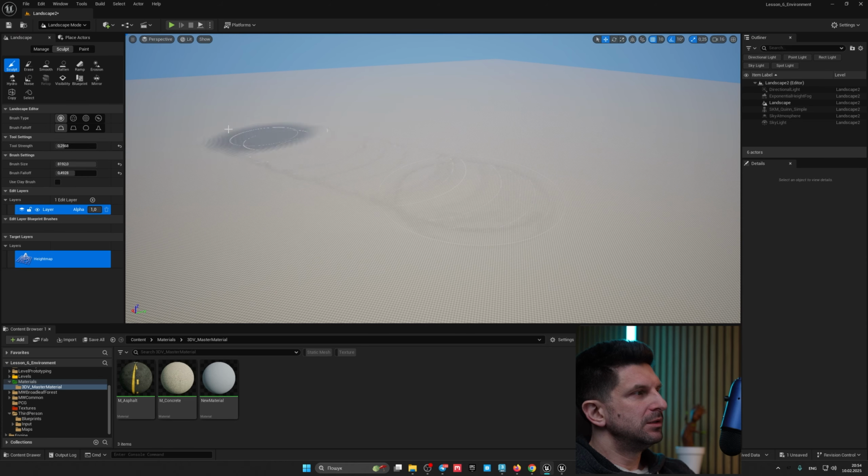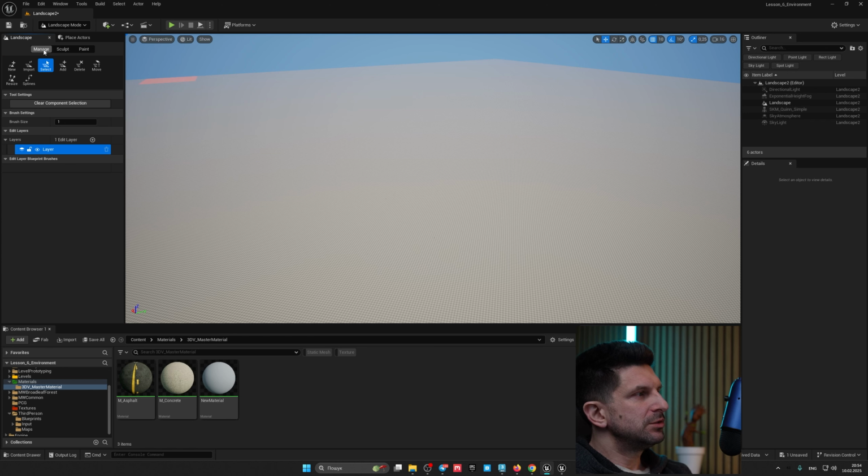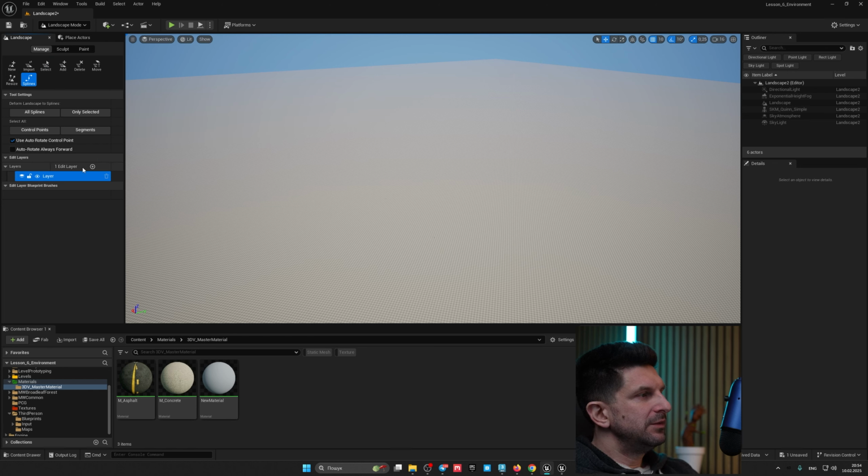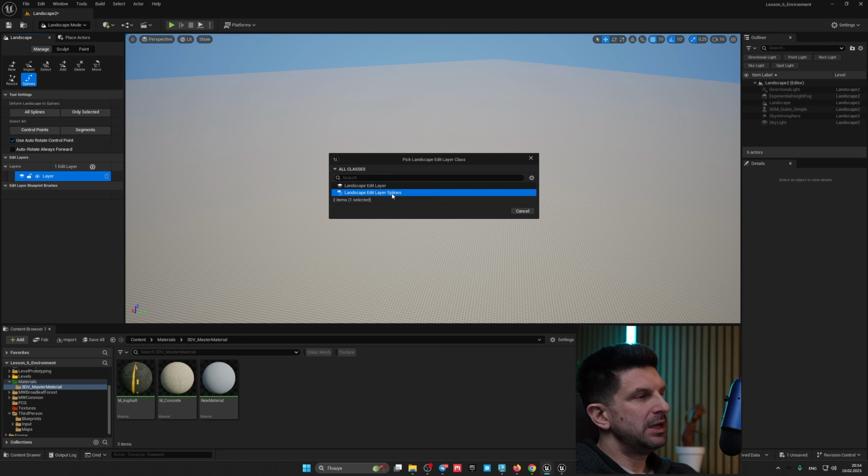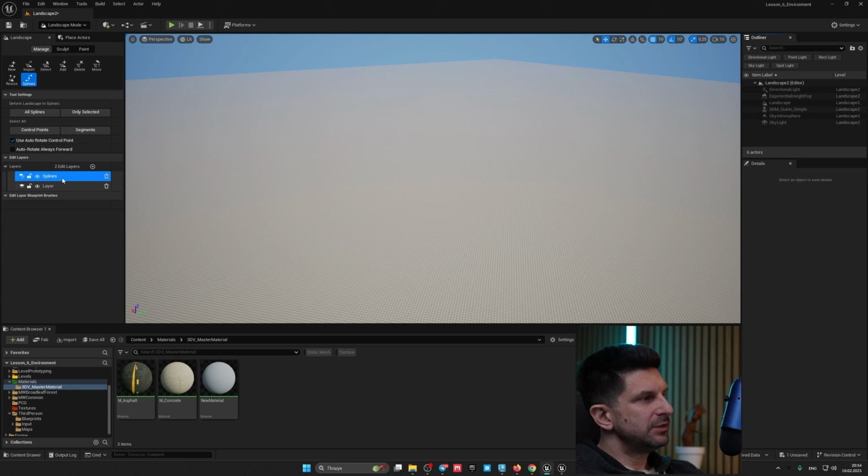That's it. And now the roads. The roads are not in this menu. The roads are in Manage. Here, where it is created, where we can add another landscape. There can be several of them. Here are the splines. Click on the spline. And look, for splines, you need to create another layer, a separate one. Click, and here there is a specific type of layer for splines. What is it for? I'll show you now. Select it, and now we have added splines.